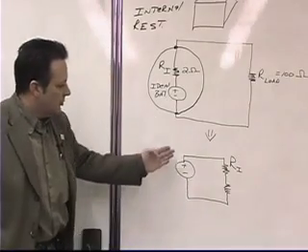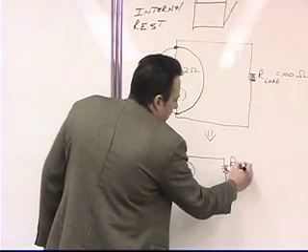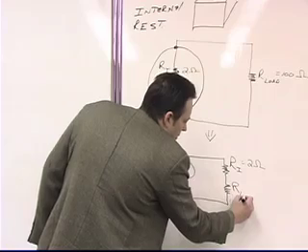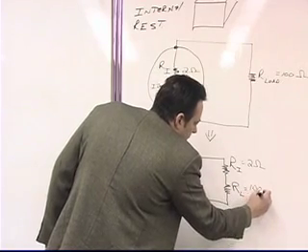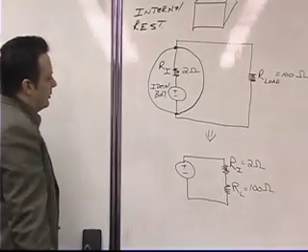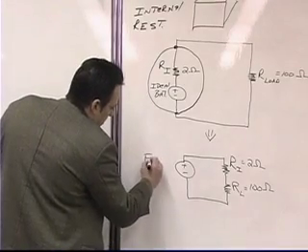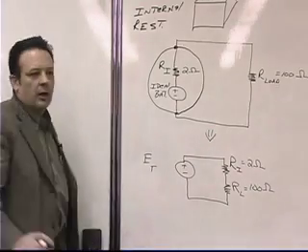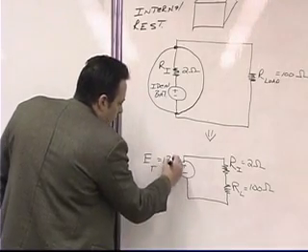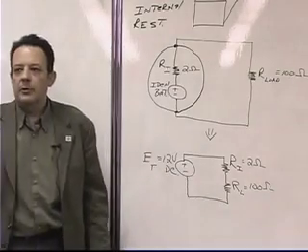So we moved the internal resistor outside of the box, and that had a value of 2 ohms. And then we bring down the resistance of our load, and that had a value of 100 ohms. And then we're going to say that our unloaded source voltage is equal to 12 volts. So we'll compare it to what we'd find in a car or an automotive application.